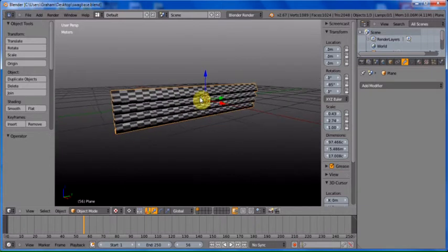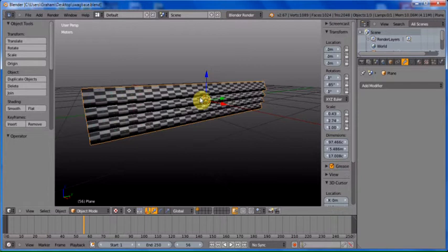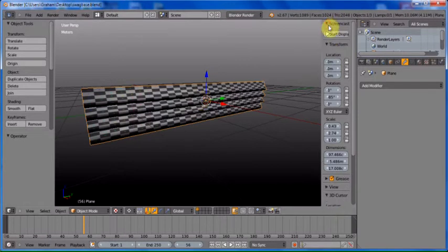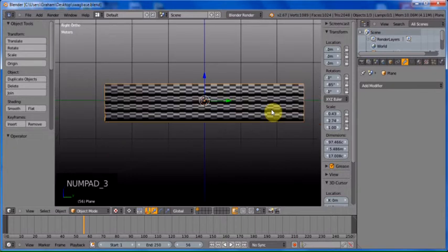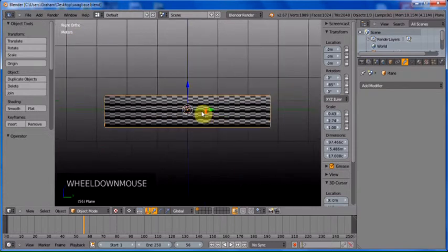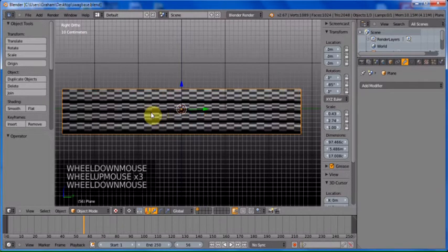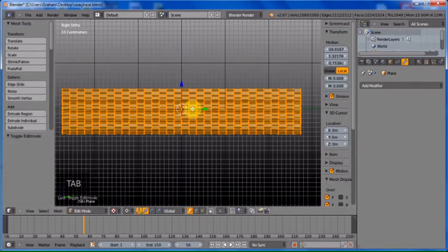Okay, now I want to talk a little about proportional editing. We haven't used this before, and it's actually quite a good tool. Getting all tongue-tied this morning. Anyway, let's go into front orthographic view. It's actually right ortho because of the way I modelled it, but I want to look at the model front on. And let me go into edit mode.